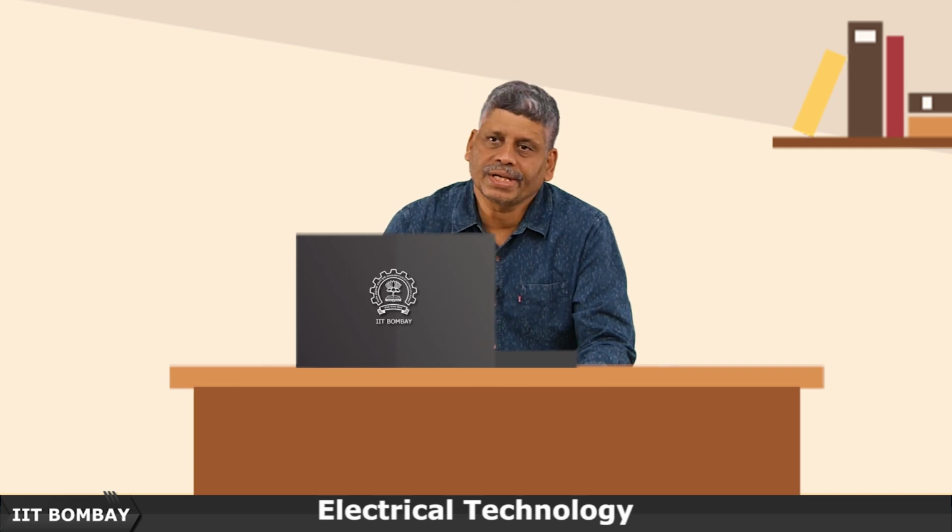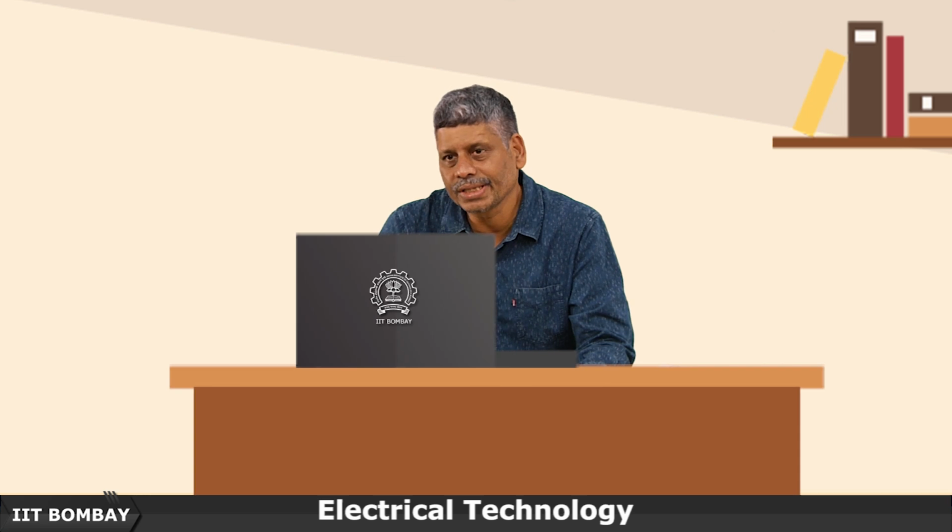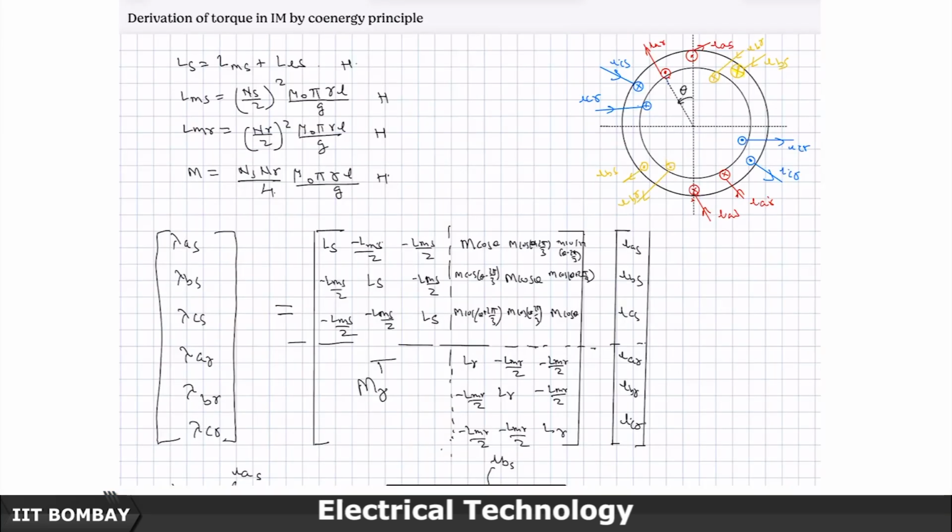Step number 2, we will calculate the co-energy associated with this complete system of the induction machine, and then we will take the partial derivative of the co-energy with respect to the rotation angle theta, and derive a torque expression and show that it comes out to be a constant, non-pulsating value for a 3-phase machine. I think we have probably done the 2-phase machine for induction. We didn't do it, we did it for the synchronous machine.